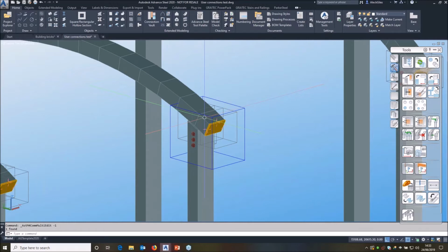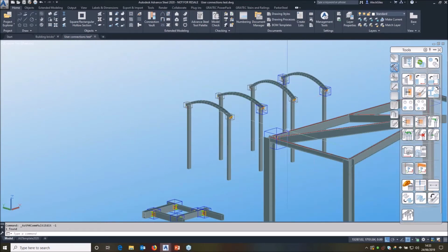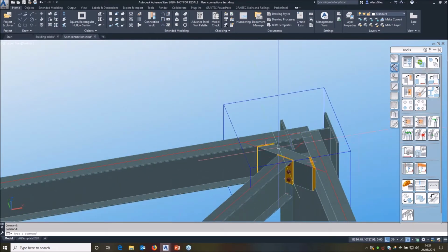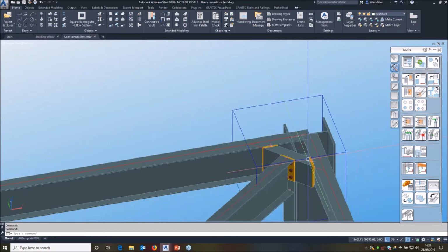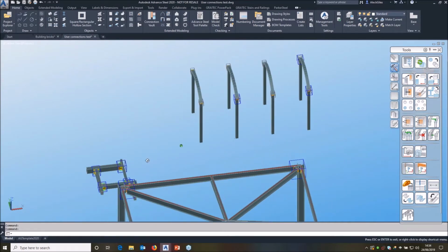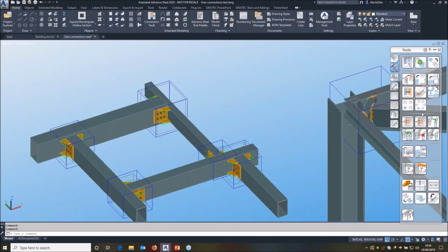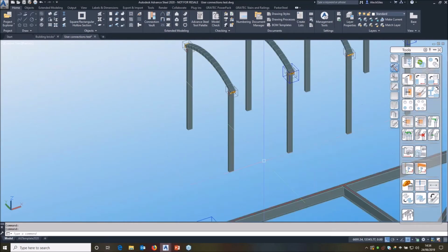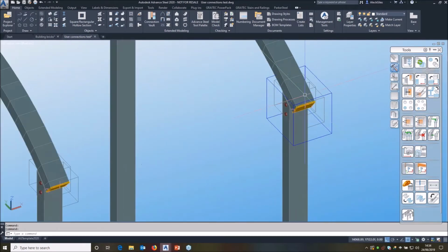So to summarize that, then, we've shown you how to build bits out of standard joints, but still put in a whole new beam in there. So you can use joints from the connection vault. We've built one using lots of building bricks and adding a small amount of variation in there. And then we've covered that on this one. The order you select things is important. Everything's based on the intersection of the 2 beams or 3 beams you're talking about. And the orientation of the first driver is the critical one.